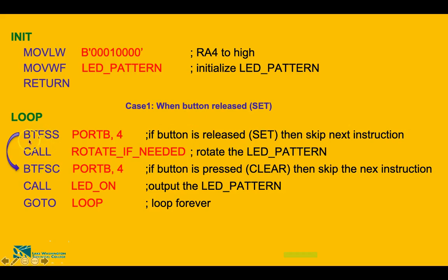So at this point, when you do the bit test for this particular bit RB4, the fourth position tells you the position of the bit. So the fourth position is your RB4 of this port B 8 bit register, and it's checking whether it's 0 or not. So let's say it is set, it is not 0. Then what's going to happen?